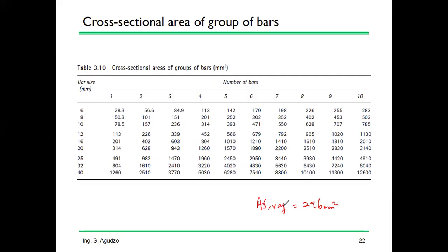Now, you have to make a decision on your diameter. Let's say I want to use 12 mm. Then I have to check from this particular 12 mm line what the steel area is, either equal or bigger.